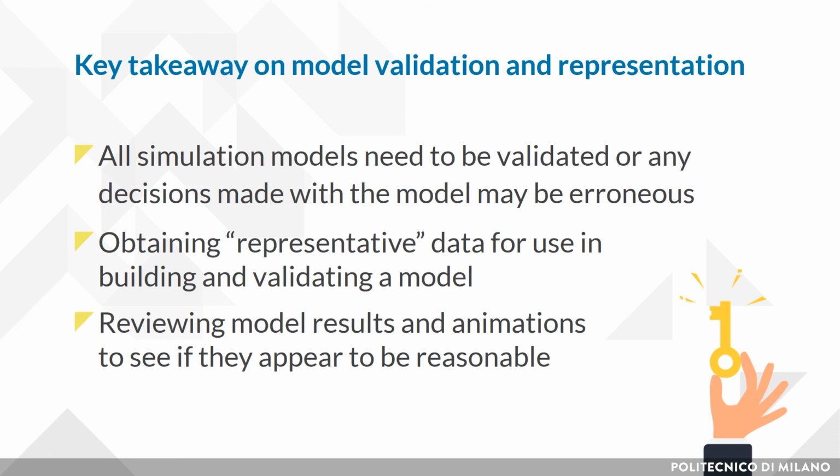Regarding the model validation and representation, we have underlined that all models need to be validated or we may incur errors within the simulation process decisions. Representative data are fundamental to obtain a valid and credible building model. And finally, review model results and animations to see if they appear to be reasonable.